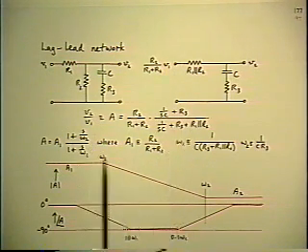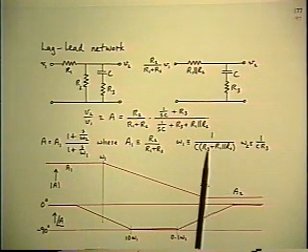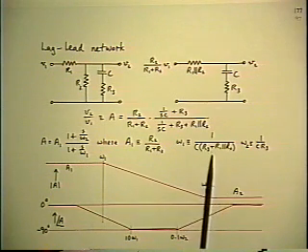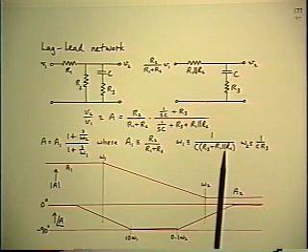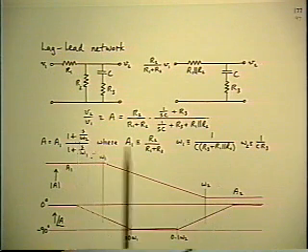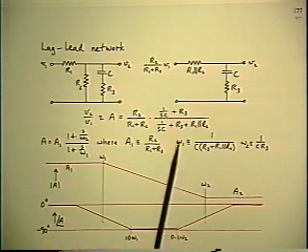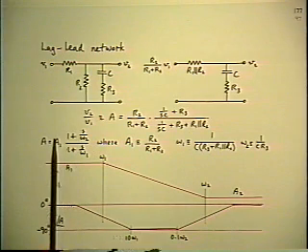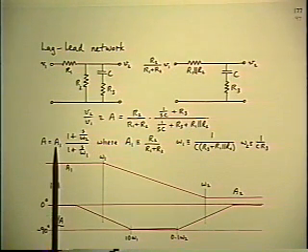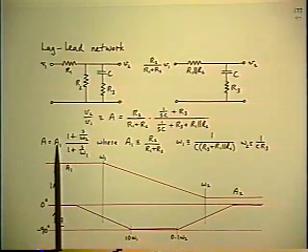One line of algebra then puts it directly into the factored pole zero form, and we see we have a pole in the denominator at omega 1, defined by the capacitance with this combination of resistances, which again is a series parallel combination. Remember not to multiply it all out. And the zero is the same capacitor together with R3. And again, having put it in that form, identify the salient features, which are the flat gain A1, which corresponds to the zero frequency gain, because if you let S go to 0, A goes to A1.